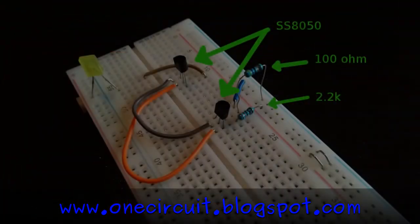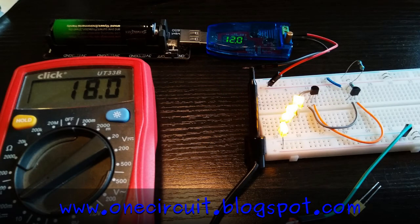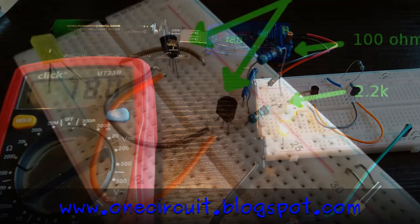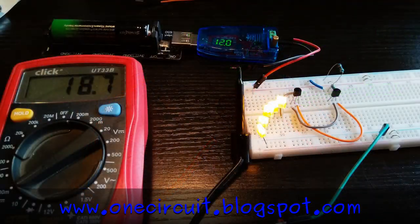and you'll notice in the background too that's 12 volts coming into this one. That's 18 milliamps with 4, so rising slightly, and 18.7 with 5. So pretty impressive. That's the circuit working.